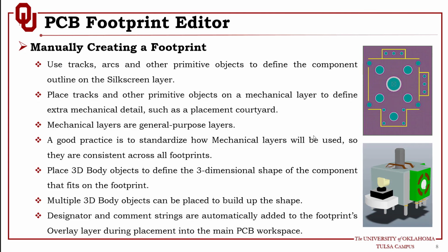One very important mechanical layer that we need to add to the footprint is called the courtyard, which defines the maximum dimension of the component. This is very essential when you do placement. You need to make sure that when you place the component on the board, there will be no collision or interference between components, because sometimes the physical size of the component might exceed, at a specific height or level, the actual outline of the component drawn on the overlay layer in yellow, as you can see here. So we'll talk about this as well.